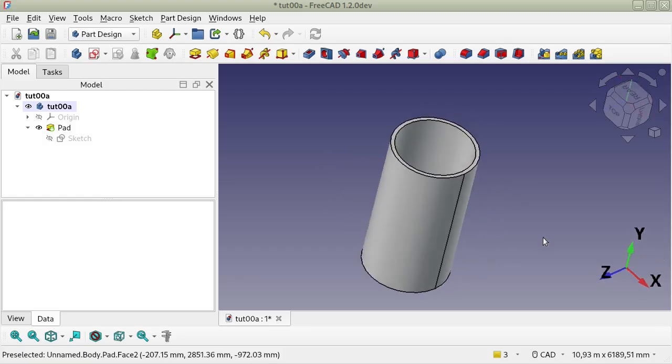For that, the Salome mesh needs an 8-corner block, otherwise the algorithm will not be available to choose. So we can have 2 8-corner blocks by axially splitting the cylinder. The splitting tool will be a plane through the diameter, and in order to create that, we need one more surface line boundary.